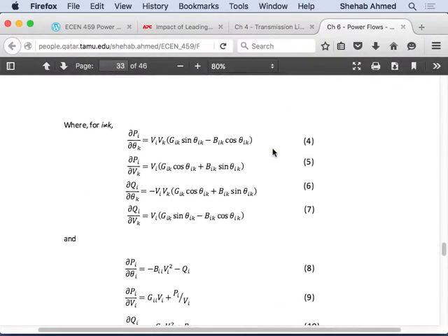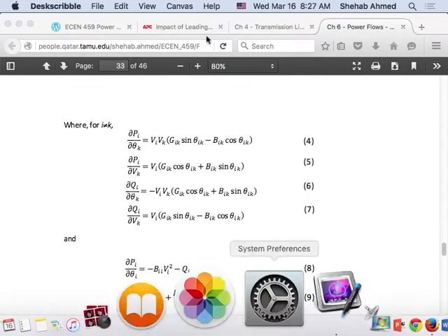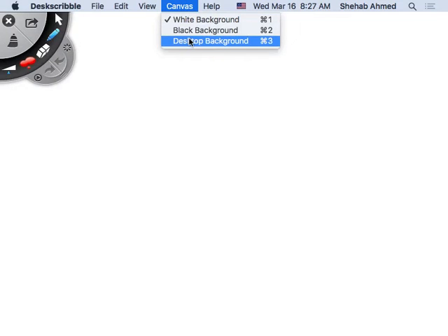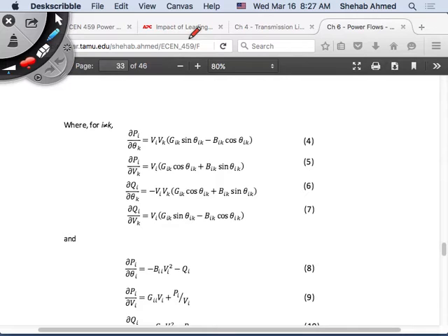Let's, for example, look at these: the derivatives of the power flow equation, real and reactive power. Okay, so in this case, what is this differential telling us? Remember, these are what we are filling the Jacobian matrix with, right? These are all the elements in the Jacobian matrix.